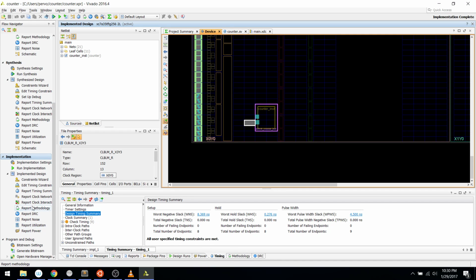Don't think I want to go into this other stuff. Yeah, let's talk about simulation. At this point, in theory, if we had an FPGA board and we're using the right pin mapping so that the clock and reset actually go where they should, then we could download a bit stream to an FPGA and go test it.